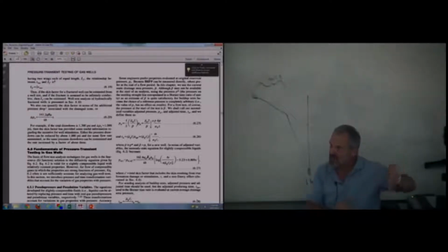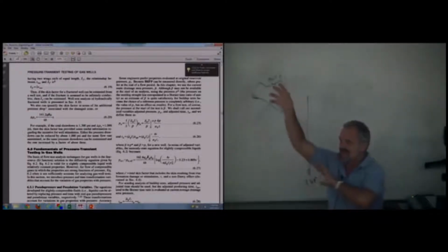You're unloading. That's another term for afterflow. Right. During a drawdown, you're unloading, and then finally those pressure transients get filled in the reservoir. Then you're producing in steady state. Right. Everything, the same rate, the same phase is at the surface. So you have wellbore storage effects on a drawdown and on a buildup. On a buildup, the terminology is afterflow, and on a drawdown, the terminology is, what did you say? Unload. Okay.